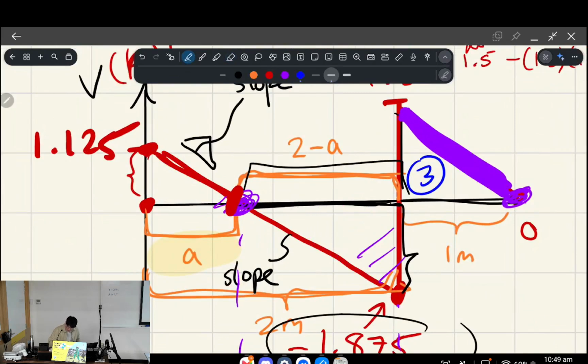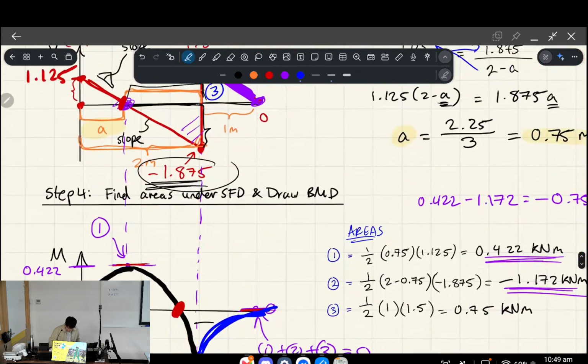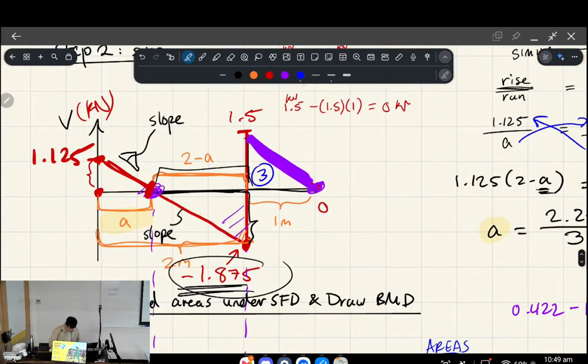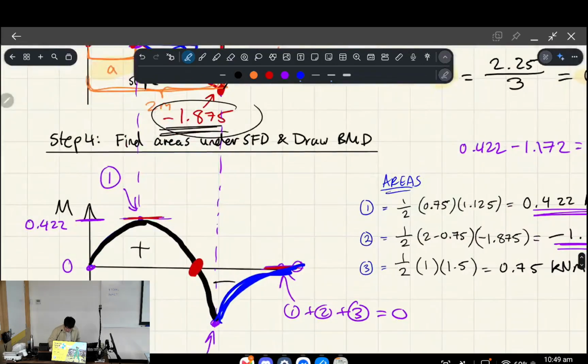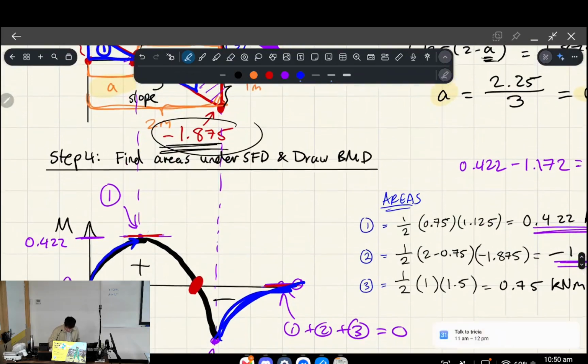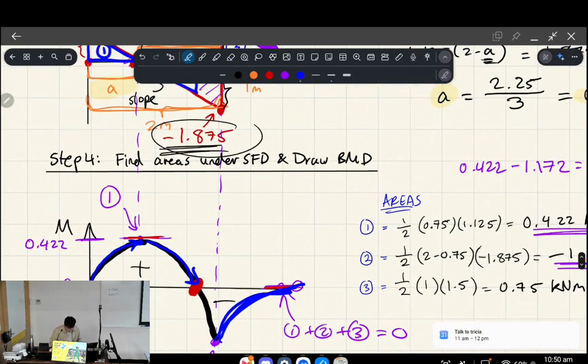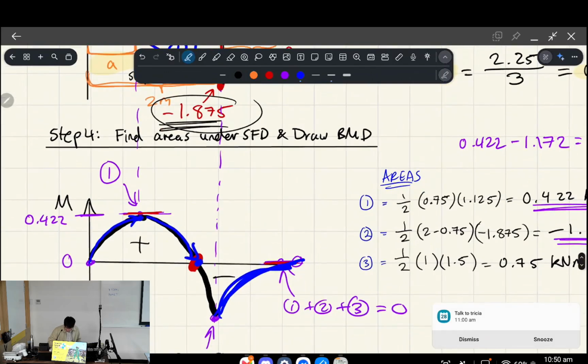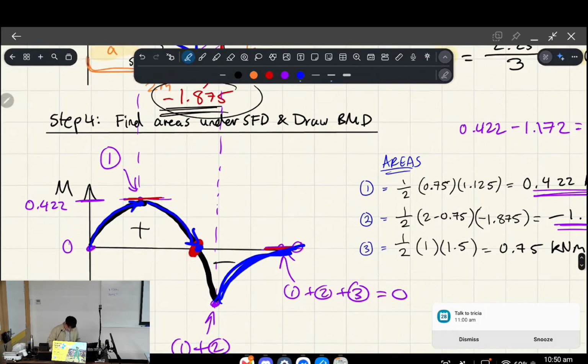So if you think about it, where the moment is 0, if you think about this graphically, is where you've added one triangle of shape 1, and then you've added that triangle again, but going negative. It's where you reach the arc of your parabola, and you go the same distance, and then meet at the x-axis.